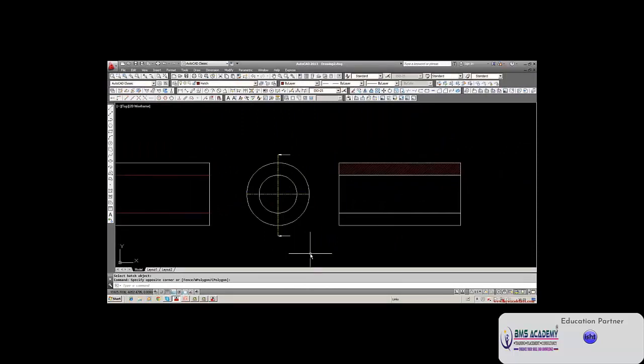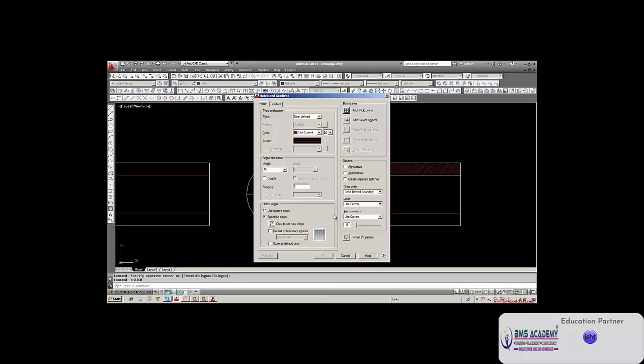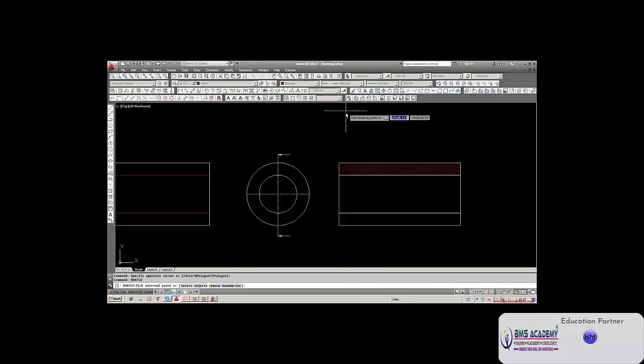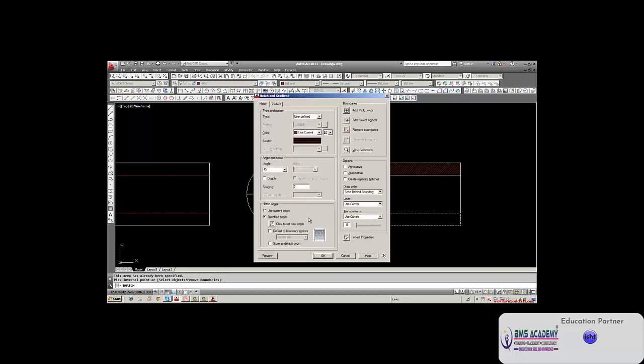So what you have to do is once again type either B hatch. B hatch is an old command, and hatch is the present command, they can use. Let us see, B hatch also it will accept: h a t c h, b hatch. It accepts it, and you click this and select this one and find out. You maintain the same value whatever you have taken earlier. This is 10, we kept 10.